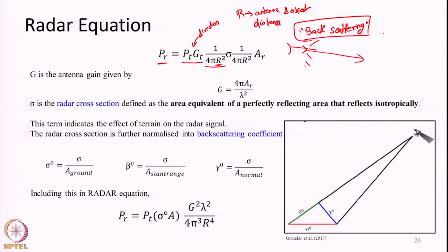This is if the antenna is considered as a point source, and this is the target. If power P is transmitted from here, it will slowly start spreading in the entire sphere surrounding it. We are going to use this inverse square law function to calculate the power received by this particular object with a given area. Now these 3 terms will define the power reaching the object of interest from the radar antenna.